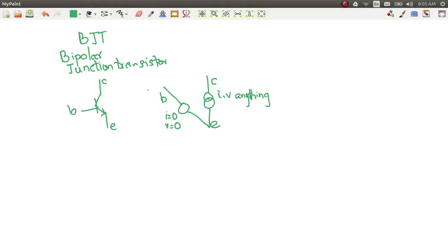So then it indicates that if the input voltage here was 100 millivolts, then the same voltage AC wise should appear here. There's also a DC offset which we are not dealing with right now, so this should have been also 100 millivolts. Now this is not the case,